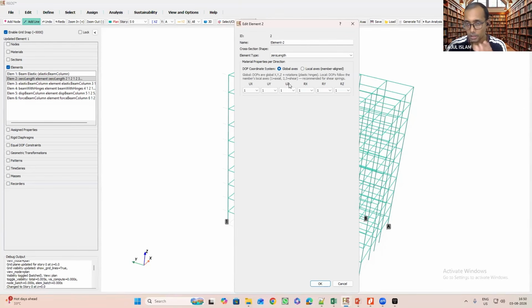So here you define the materials for each of the degrees of freedom to simulate the nonlinearity in particular degrees of freedom. Now, in this demonstration, we'll only simulate the nonlinearity in the flexural response. Then other degrees of freedom will be provided with the elastic material.